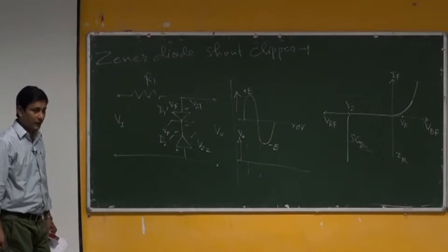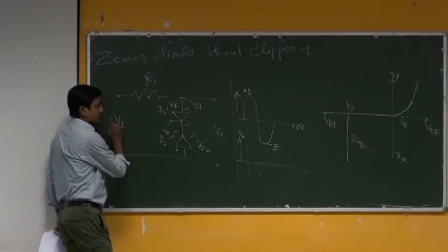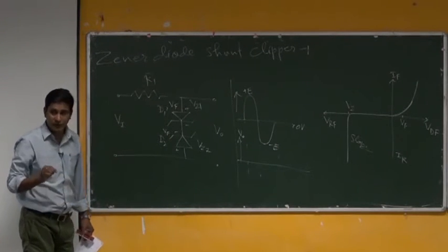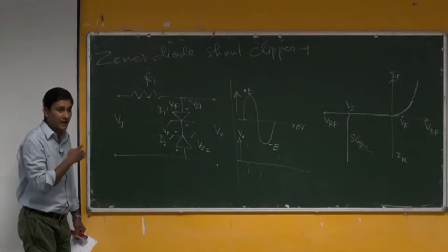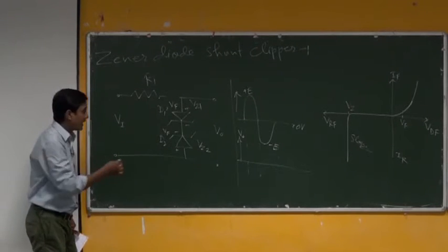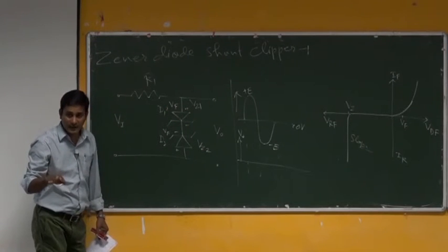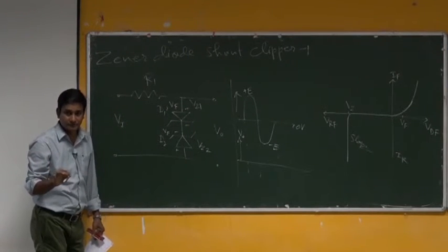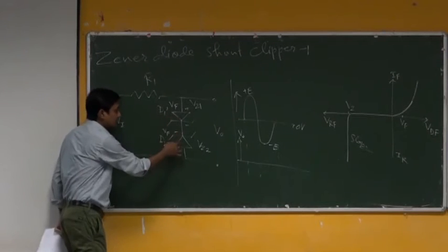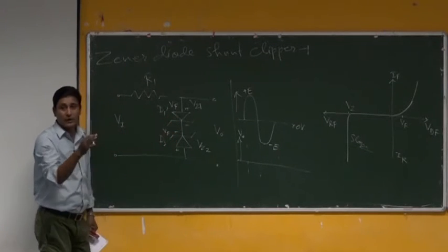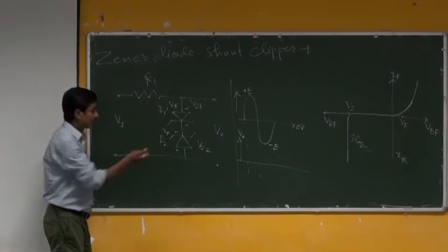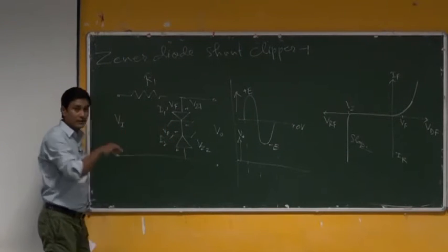So if I analyze this circuit, what minimum voltage should I need to apply here, so that one diode at least will be conducting and the other diode will be non-conducting at the beginning? Because I am saying these two diodes are connected opposite to one another, one P to N, another N to P in the same circuitry.